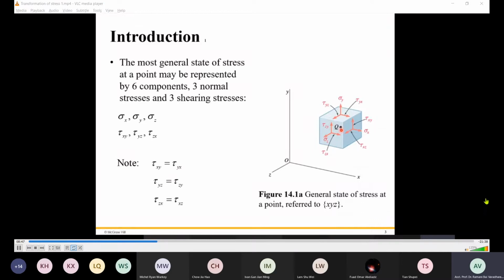This is a plane, right? Plane means just imagine the floor. The circuit is on the floor, the system is on the floor, the lines are on the floor. That is plane. It's on the floor. These two are on the floor. This one is perpendicular to the floor. So these tau xy, tau zy and tau zx are on the plane. These are the shear stresses and a normal stress. So any element will be subjected to these three.